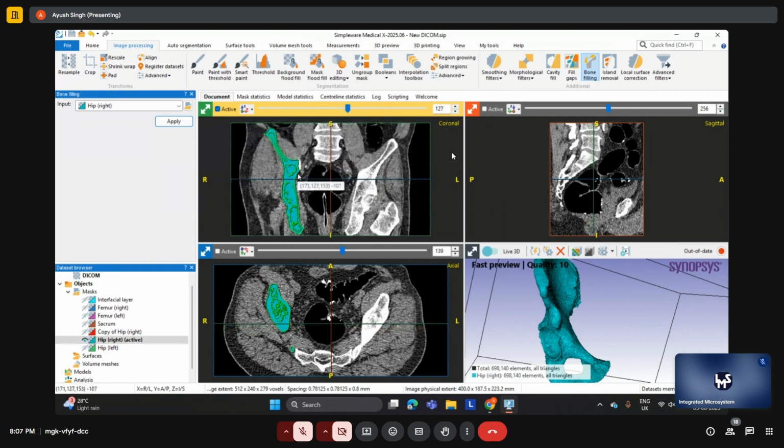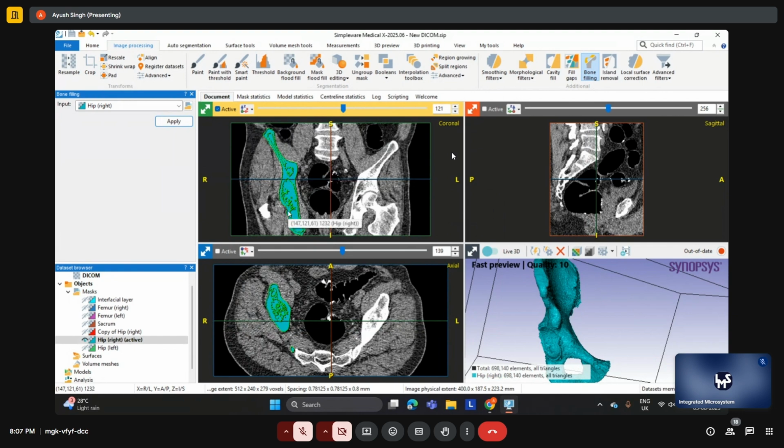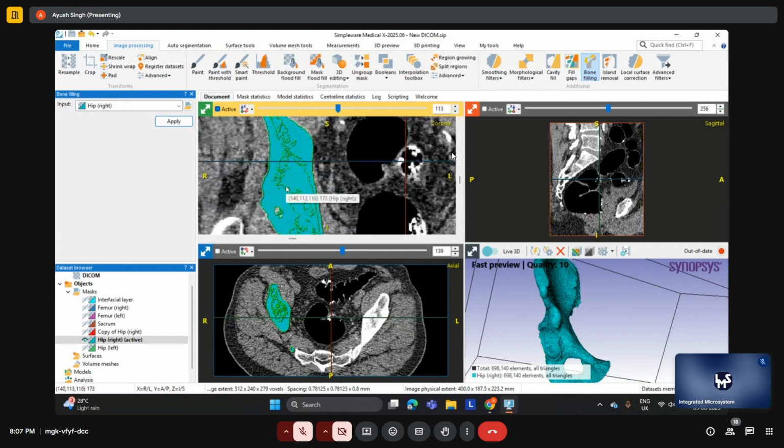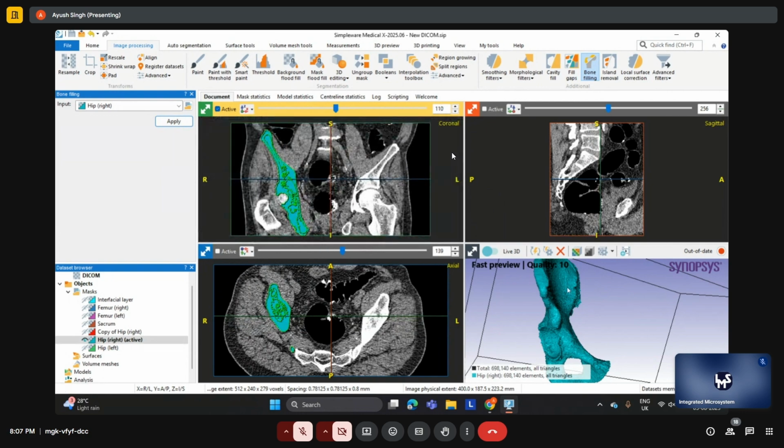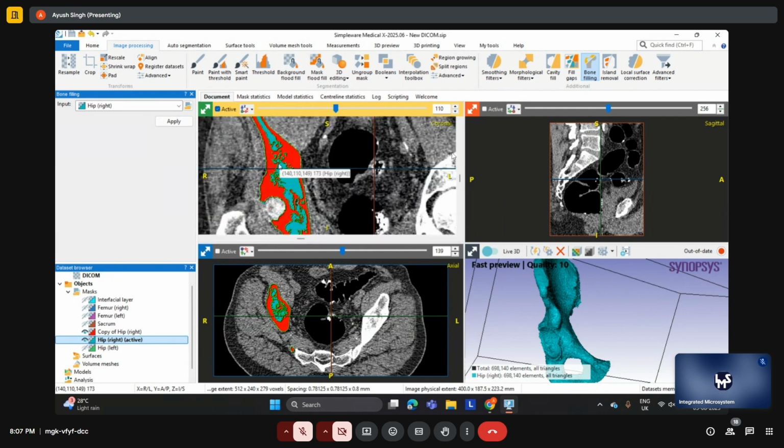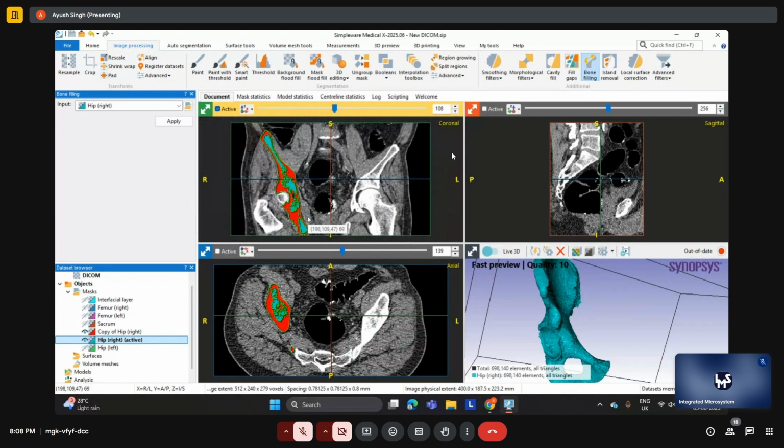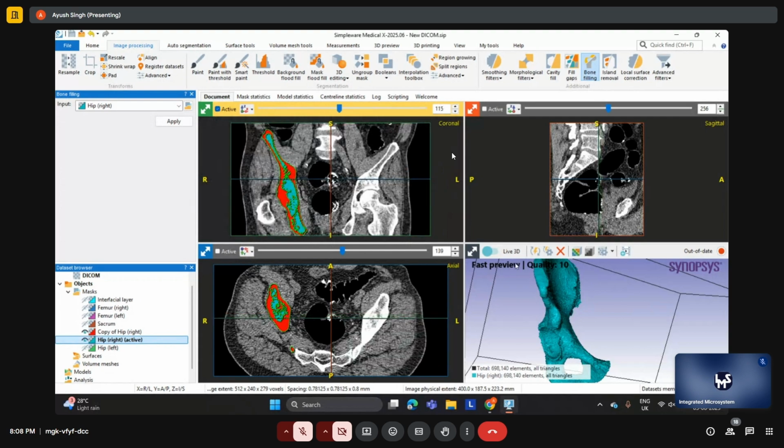So we can see the resultant changes in the 2D view. We can also check the contour levels that it has filled up, and if we need to check the 3D contours, that too can be done. That is one such possibility. If we compare it over here, all the blue region that is getting highlighted is the filled up region that we have solidified using the bone filling operation.